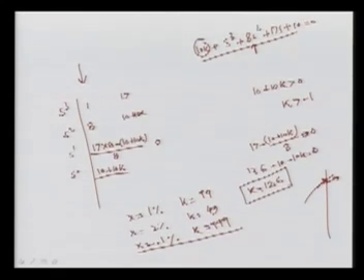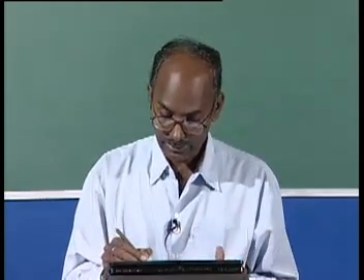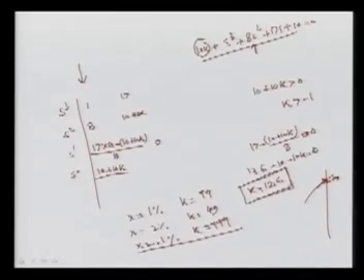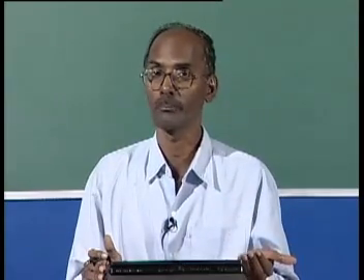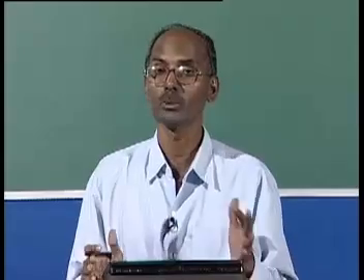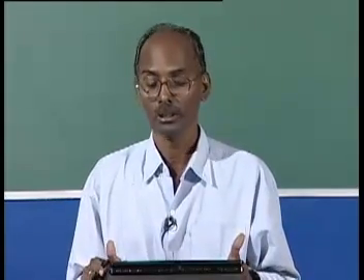So the time constant gives your dynamic response, and this value decides the stability. Means if you are increasing the gain more than this, you will, no doubt, get more static accuracy, but your system AVR loop will be unstable.